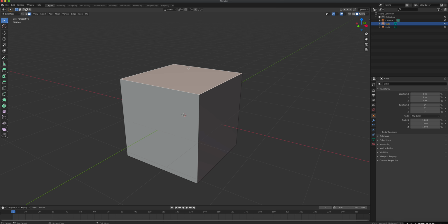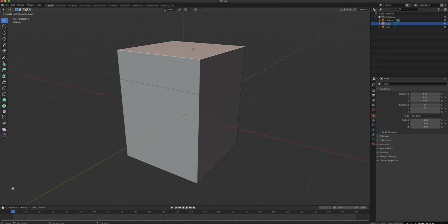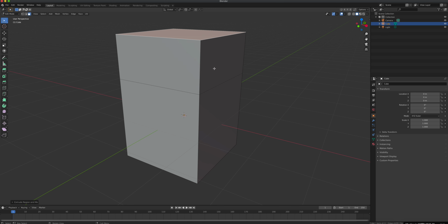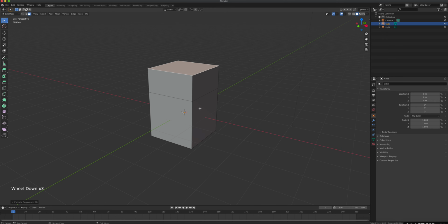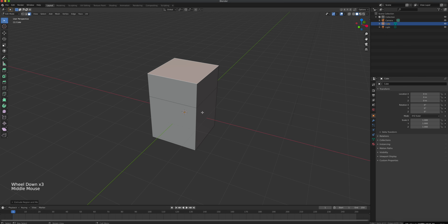So if I select this top right here and I press E to extrude it and I move the mouse up, I get an extra one. Okay, so basically I extruded this cube, now it went up like so. Okay, but that's using a keyboard shortcut. So let me click undo. Okay, what I want to do here is use the extrude tool instead of using the keyboard shortcut. So right here is your extrude tool. If you're not sure which one of these, right? By the way, they won't show up like this unless you're in the correct mode.